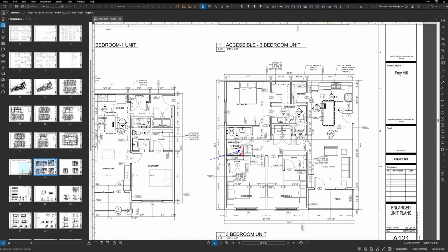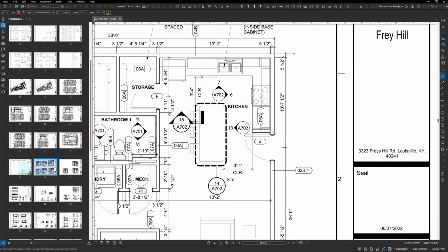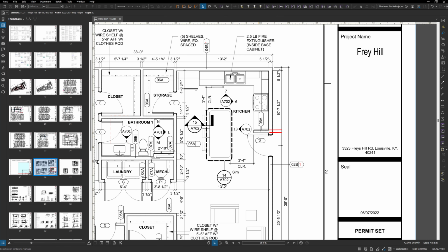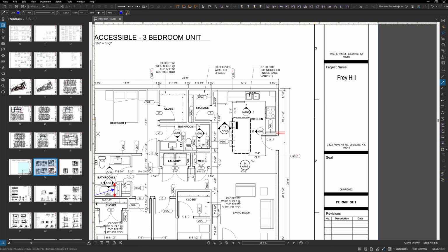Little itty bitty dimensions, it's nice if I can catch some of these things. I don't know why these particular dimensions that I'm showing right now have a tendency to just disappear job to job, and they have to go back and be added in. Here's another example: the door shouldn't be dimensioned, the wall should be dimensioned. Once you dimension the wall, the door is in a 90 degree corner, and then the door's dimensions are not necessary.